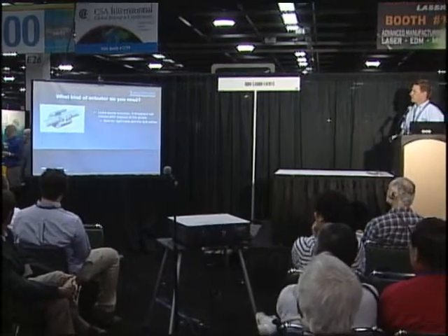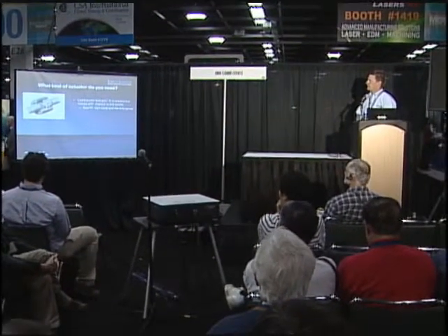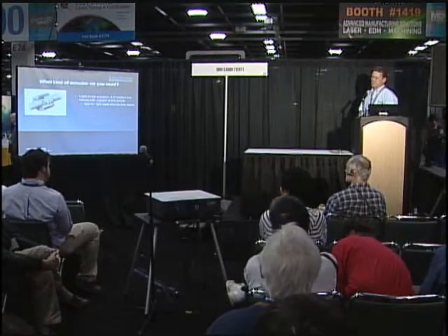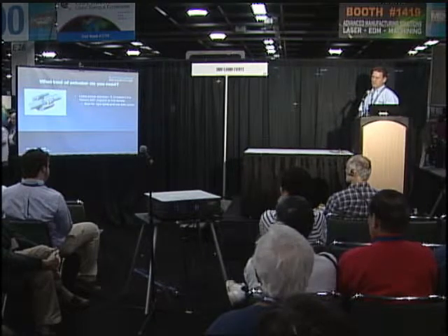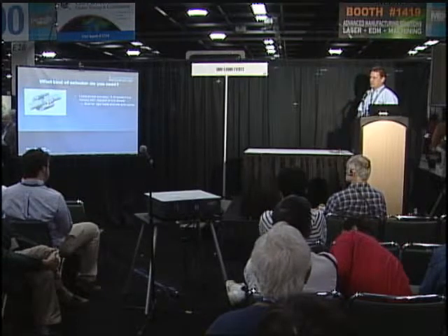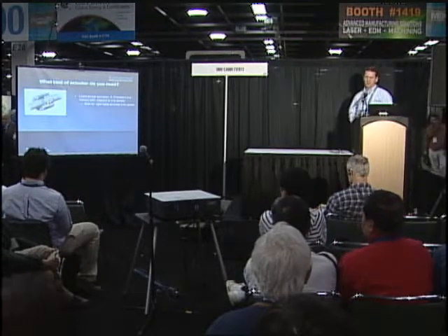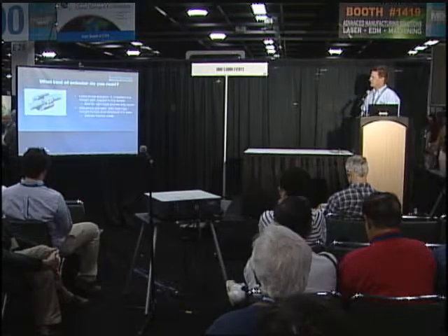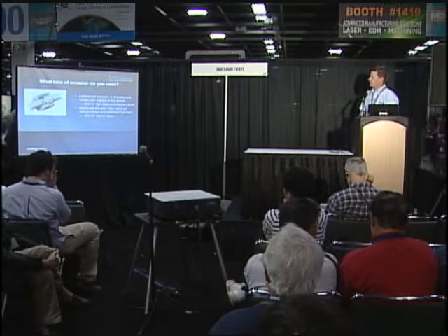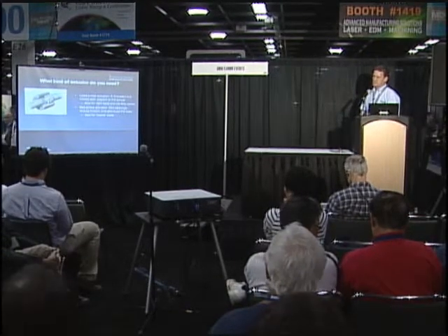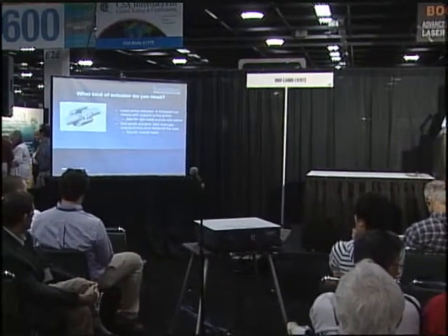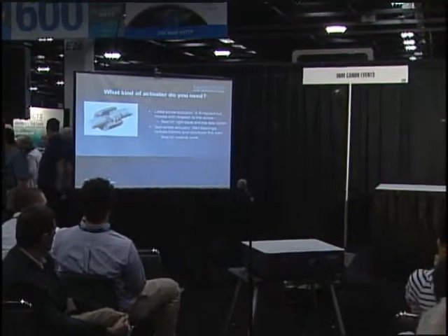So when you're looking at what kind of actuator you need, in the picture here you're looking at a ball screw. Those are typically very quiet, but they're very expensive. They translate the forces very well. They can handle the thrust and radial forces as well, but they are typically very expensive. You have to be careful about the environment with these. If you don't have sweepers on the screws to clear off any debris, then you can run into problems of damaging the balls.